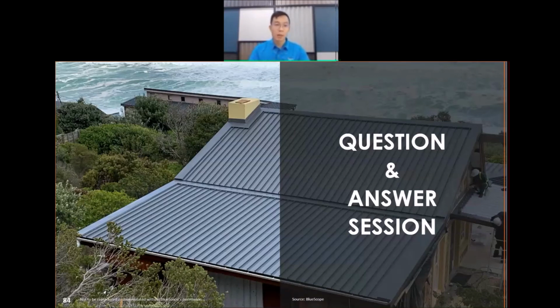Sometimes people will consider, hey, how about stainless steel fasteners? Would it be suitable to be used? Currently, based on our experience and observation, stainless steel fasteners in those environments would cause premature corrosion, if it's a typical stainless steel fastener without any additional component. The reason is that once it's fastened onto the profile, it would be in direct contact with the steel cladding. And this will cause what I call a galvanic reaction, because stainless steel paired with zinc, aluminum or steel will cause a reaction, same like copper with steel that we covered in the previous Steel Connect webinar.